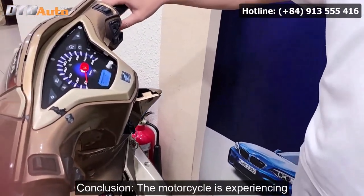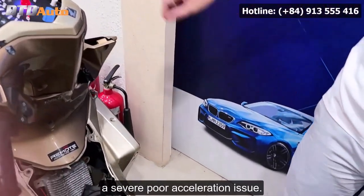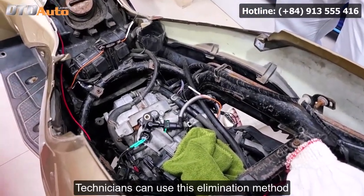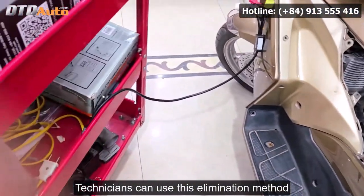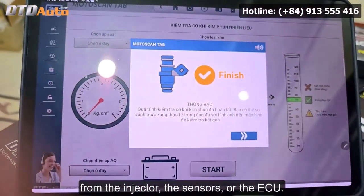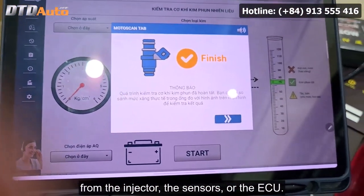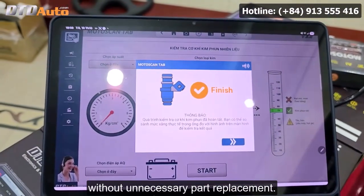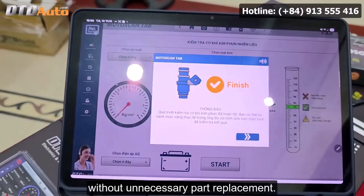Conclusion: the motorcycle is experiencing a severe poor acceleration issue. Technicians can use this elimination method to quickly determine whether issues originate from the injector, the sensors, or the ECU. This ensures accurate troubleshooting without unnecessary part replacement.